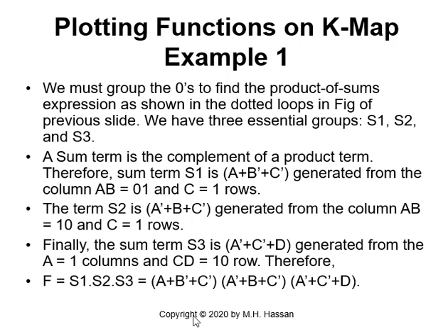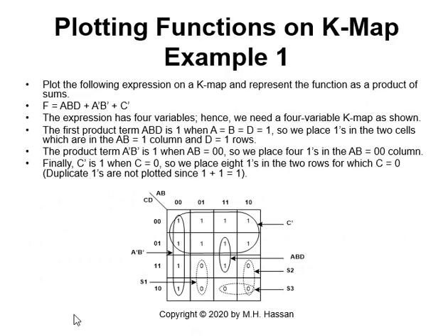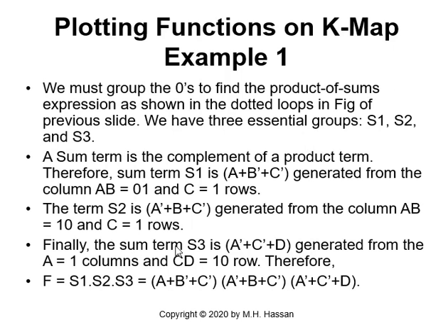The term S2 from the map, we have A prime. We just complemented. A is 1, we take A prime, B, and here for S2, the 1 will cancel with the 0 for the B, and C prime. Okay, so S2 clearly will be A prime or B or C prime.